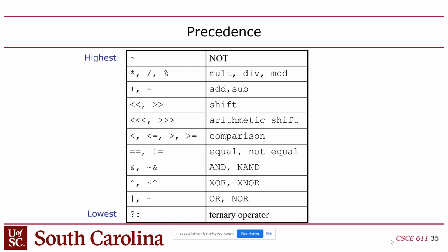Now, this is a little weird too, because I mentioned that Verilog doesn't really have types other than bit vector, or what they call logic. But a multiply cares about type. If you multiply something by a negative number, it's different from multiplying it by a positive number, right? That's where things get a little strange. Sometimes, and we'll do this in our ALU, you have to use a special function to specify whether the operands are signed or unsigned. So be a little careful.